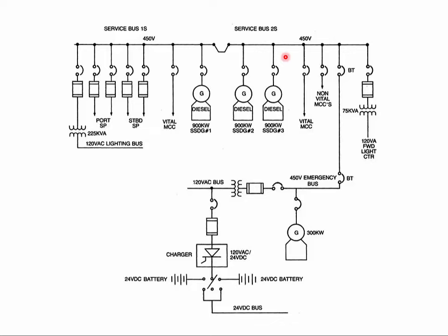And on some systems where you're doing this manually, it will allow you to do it because it is not looking for that generator. So anyway, whenever you are on feedback, you should lock out, tag out your main generators and not go anywhere near this. If you were to put a main generator on the line with the emergency diesel generator without being properly synchronized, the fault current created can destroy equipment and destroy the board, and it is absolutely not allowed.